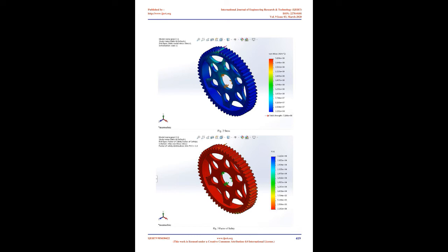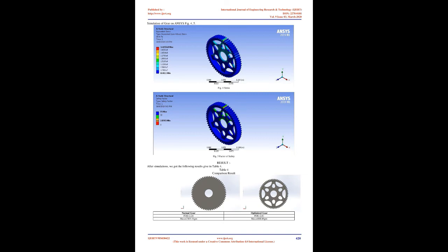Calculation of tangential force. The two components of net force on a gear tooth are radial force, Fr, and tangential force, Ft. The only force responsible for gear rotation is Ft, calculated below. Ft, tangential force applied on gear tooth. Ft equals 2*Mt/d1. Ft equals 2 * 451,000 / 147.5. Ft equals 6,101.6949 N.